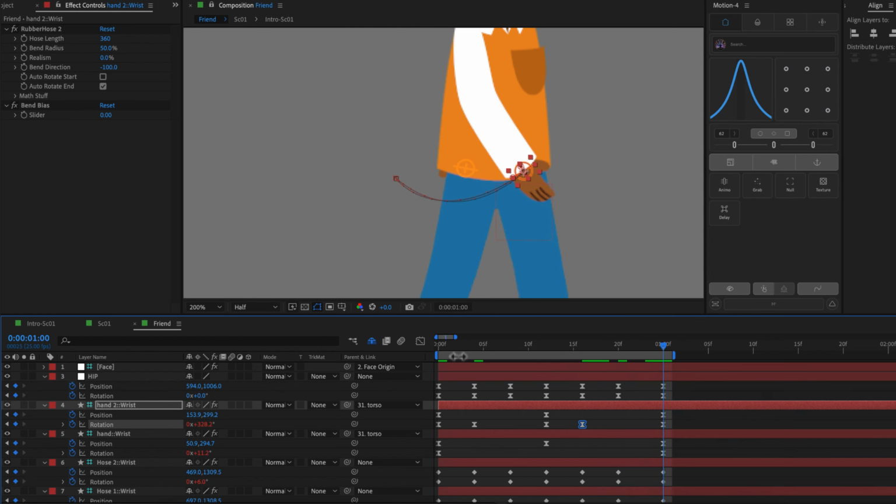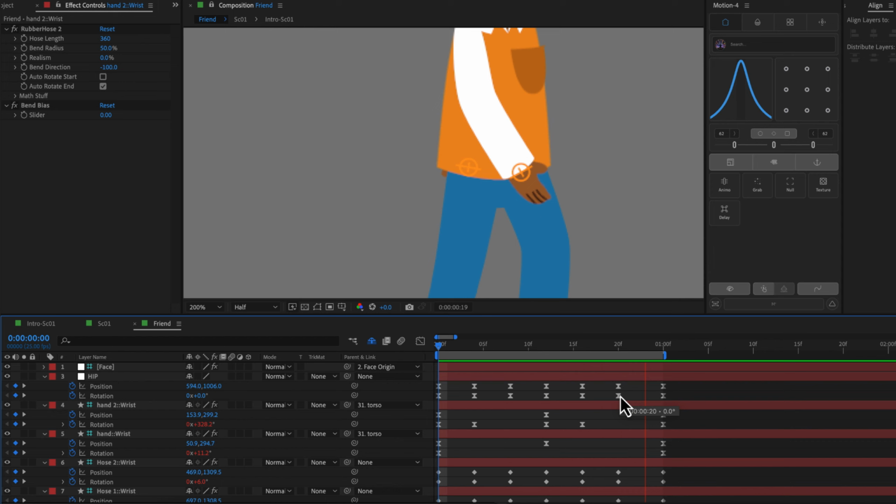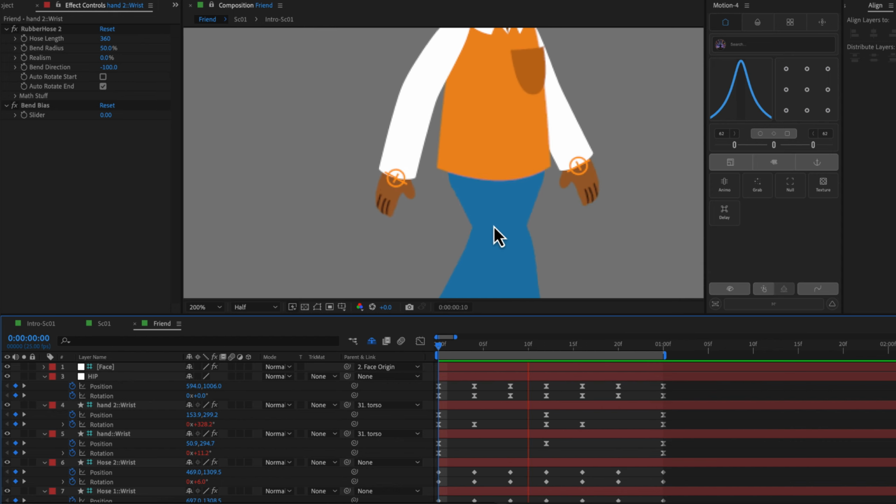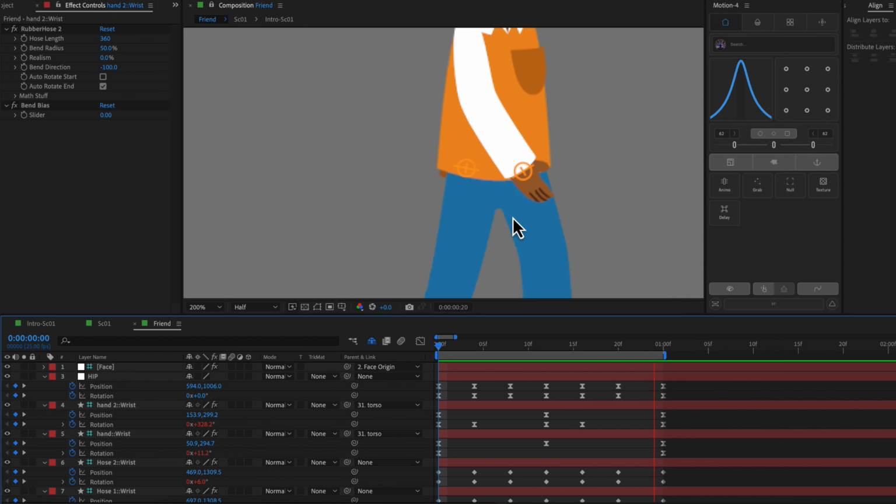Alright, since the first and the last frame are the same, I'm just going to go to the second last frame and press N on the keyboard to limit the time slider. So it goes to the 23rd frame and then goes to the 0 frame again, which is the 24th technically. Okay, so it will not play these 2 frames twice, and our character will not look stuck for 2 frames. Okay, this is just a technical thing for looping the animation. Let's test this, and there you go, your hand looks really smooth.